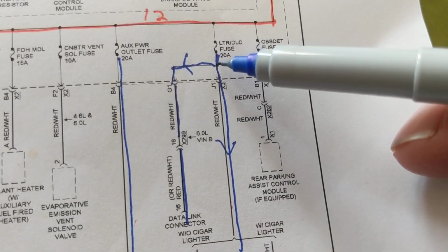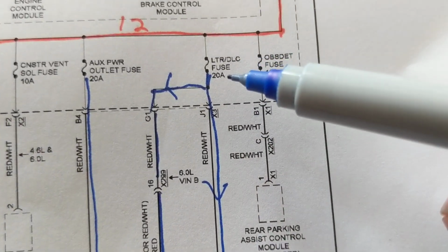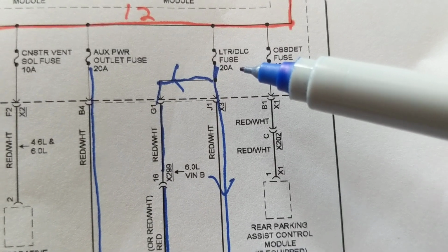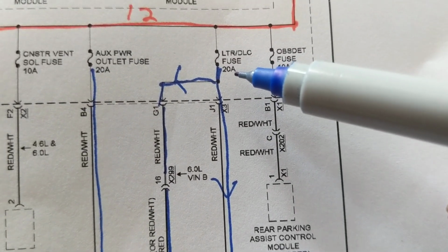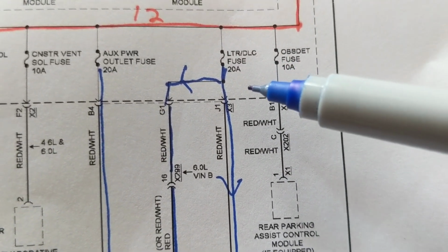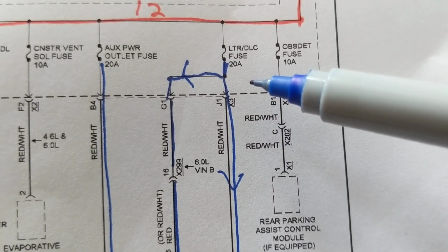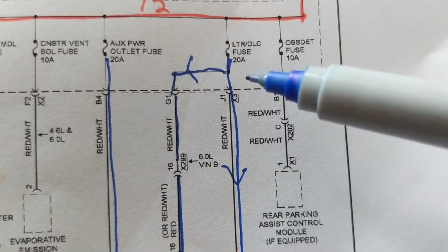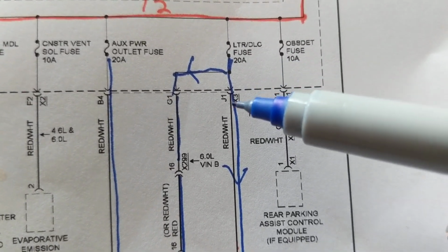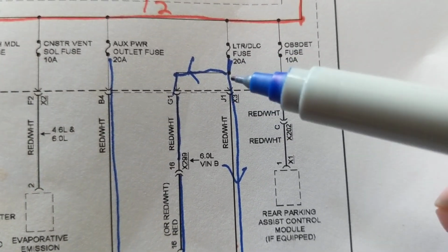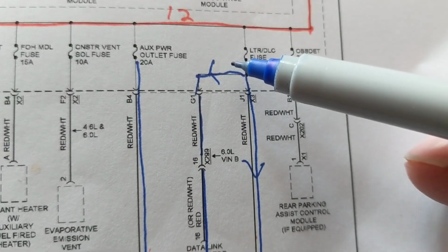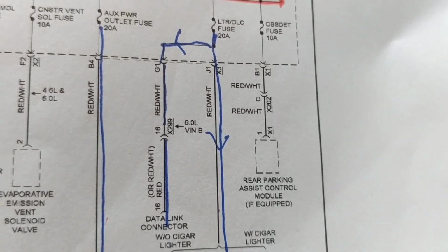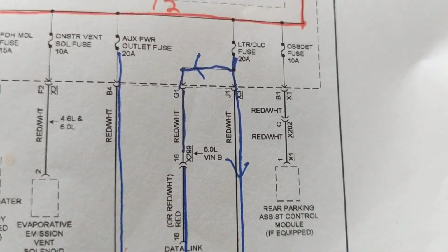Now, I see another path over here. We're dealing with obviously the lighter DLC fuse, rated at 20 amps. As you will see, there is a color code for the fuses. They could be green, they could be yellow. Yellow is usually 20 amps. 15 amps, some are red, some are green, according to the color code. So sometimes they have, obviously, the amps written on them. 20 amps, 30 amps. But let's say it's erased.